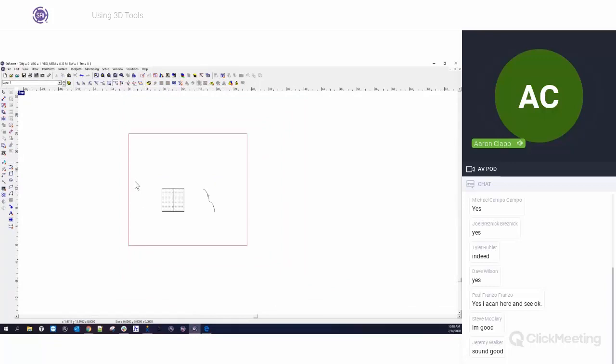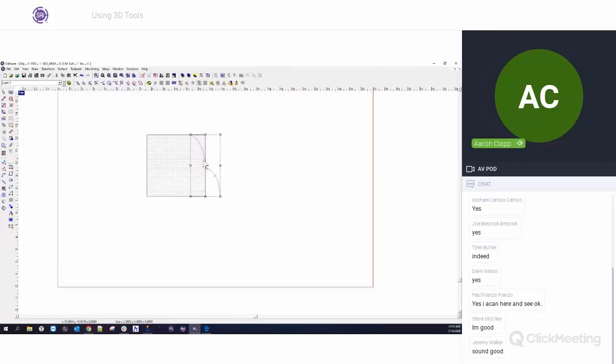And again, another really simple, easy to use tool, not too complicated. Some of the things you just have to remember is, if you're not going to use a contour line like this, the best thing to do is to place this object right on top of the relief, so that it creates that relief right there on top of it, because it just revolves it in place if you don't tell it where to revolve.